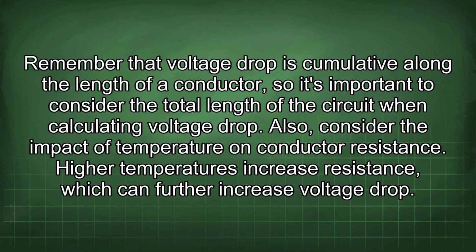Remember that voltage drop is cumulative along the length of a conductor, so it's important to consider the total length of the circuit when calculating voltage drop. Also, consider the impact of temperature on conductor resistance. Higher temperatures increase resistance, which can further increase voltage drop.